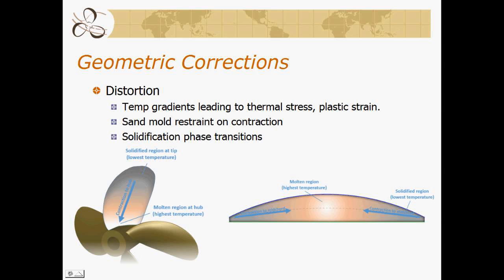I have another question here. Does it offset each face, or does it split the offset? So these offsets are specified specifically per face. So if we add 1/8 of an inch to the face and 1/8 of an inch to the back, we will have a total added thickness of 1/4 of an inch.